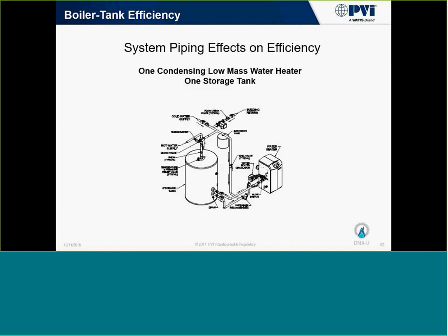The other thing that needs to be taken into consideration is all the additional piping and pumps, and along with the pumps, the electricity that's used in order for that system to be installed properly. So the piping is a little more convoluted, a little more flow dependent to protect those heat exchangers. For instance, if the facilities maintenance guy replaces a pump in that system that's not designed for that heat exchanger, then he could be burning through heat exchangers because it's not flowing enough. Or he could be eroding the heat exchangers because it's flowing too much.